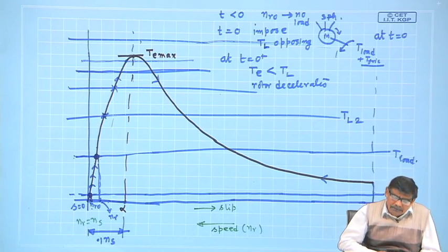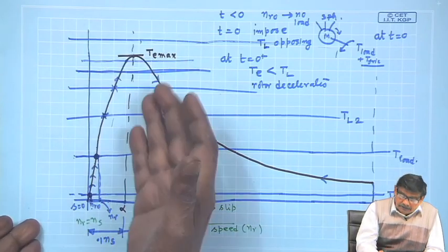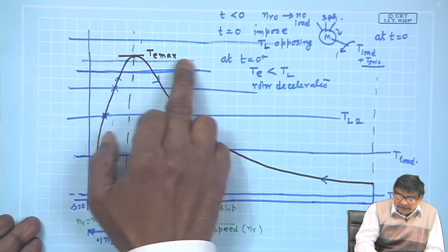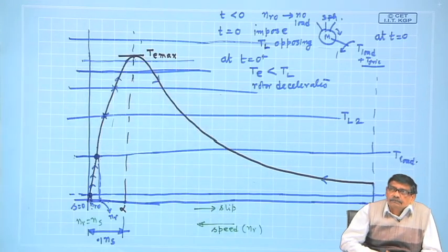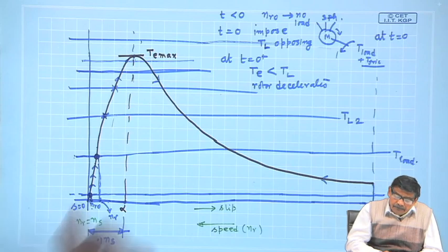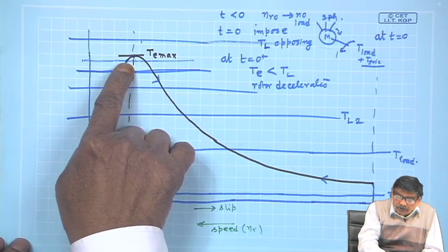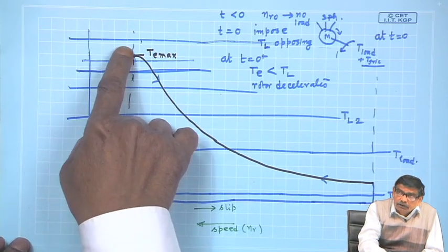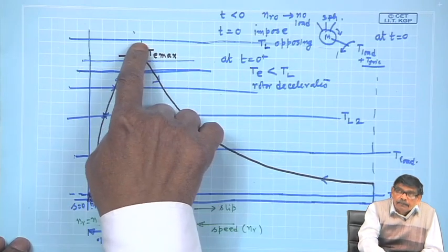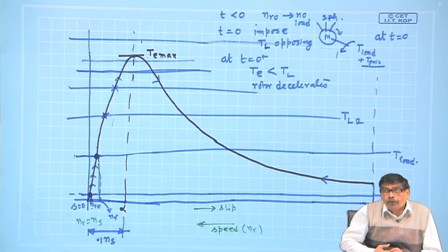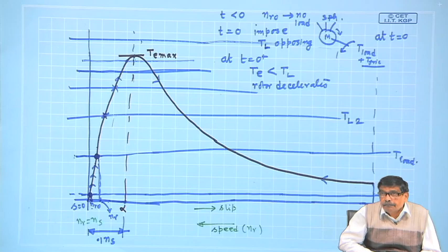It may so happen that load torque suddenly increases by a small percentage on this side, then you are gone. If by chance load torque increases by 10% or 20%, it crosses that dreaded point, where the machine will not be able to recover and give you a final operating point running steadily at some RPM.